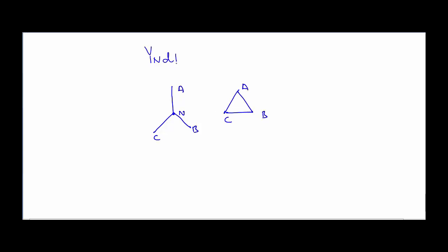And since it is 1, it's obvious that it will be lagging by an angle of minus 30 degrees. So what we are going to do is rotate it by an angle of minus 30 degrees. What we mean is that we are going to short this A and this A together. I have written it as capital A, capital B and capital C. I'm going to mark it as small a, small b, and small c, in order to indicate that they are the low voltage side of the transformer.